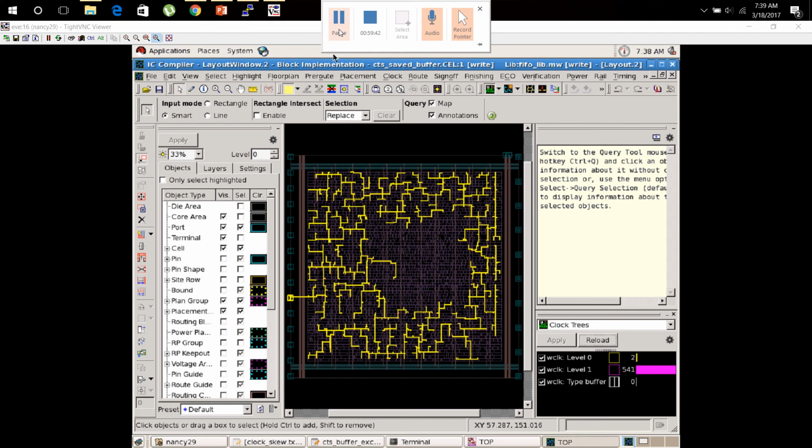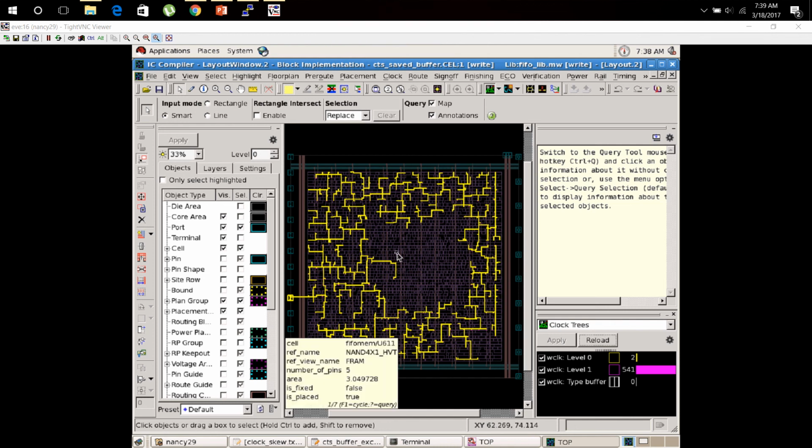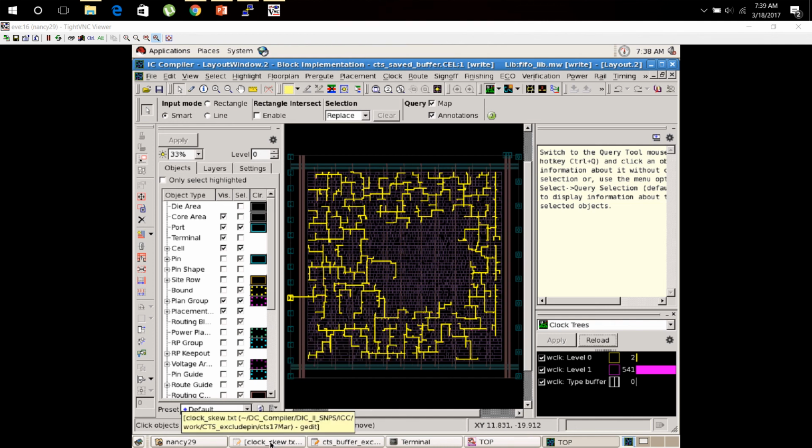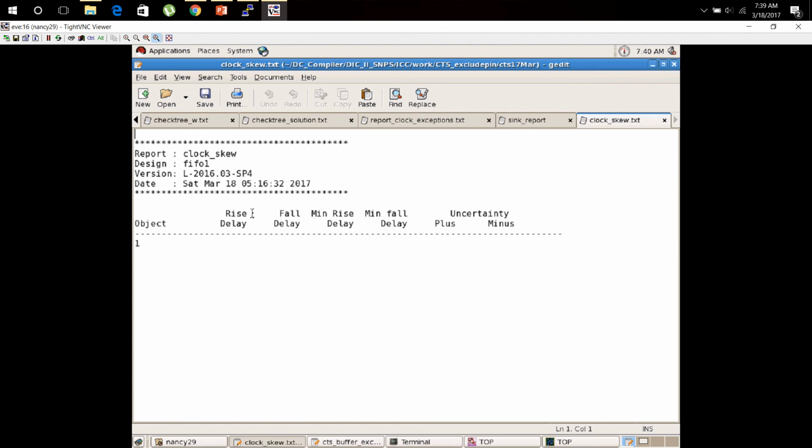So we can show you that after doing clock tree synthesis and analyzing different types of clock optimization options, there are no skews in the circuit. If we are doing high performance designs which have more sequential circuits or flip flops, we get some kind of skew, and we can remove these skews from the design using fine tuning and all of the different options available in the ICC tools.